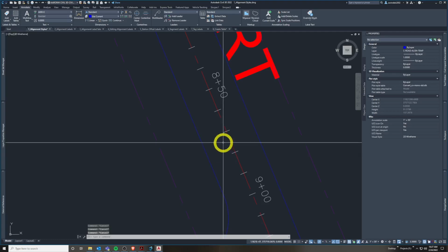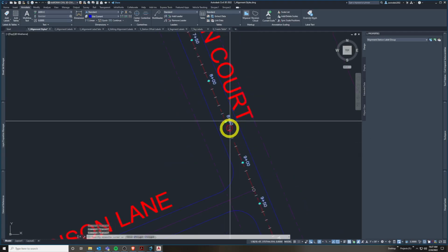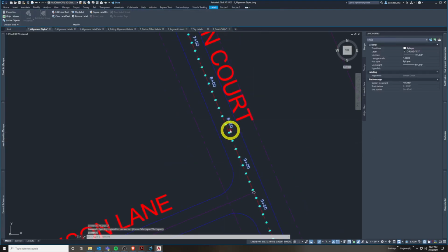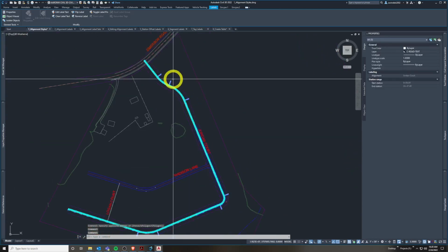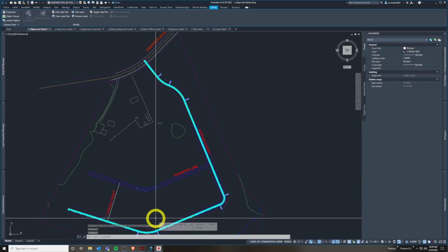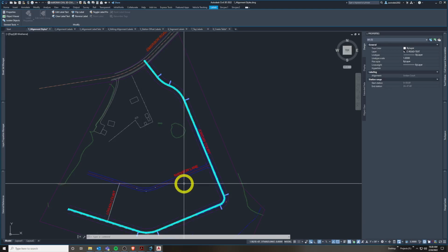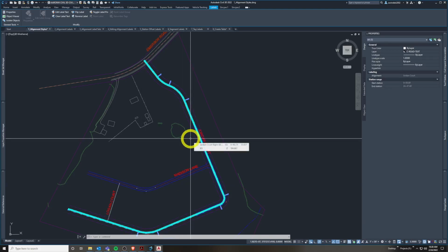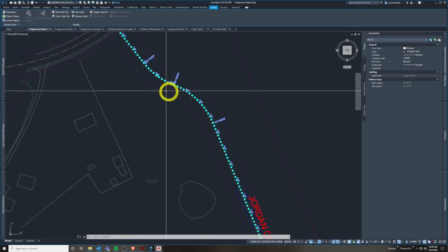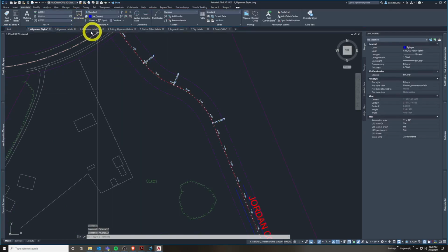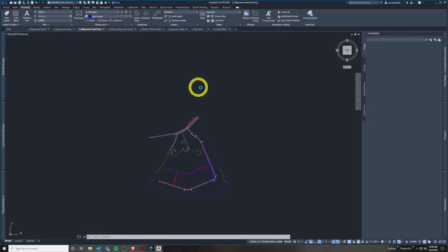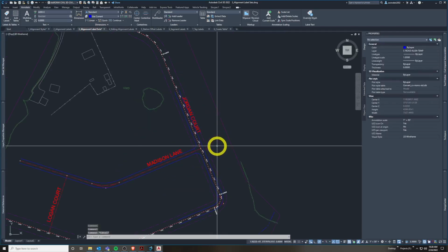We're going to learn about saving all this stuff I just did at once. I'm clicking it right now in the geometry labels. How do we label all these things at once in one step, let's say? Glad you asked, because that's what exercise 6.3 is all about. We're going to save this label set as a group to do at once. So let's go to the third file, alignment label sets.